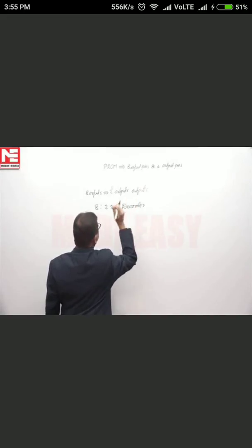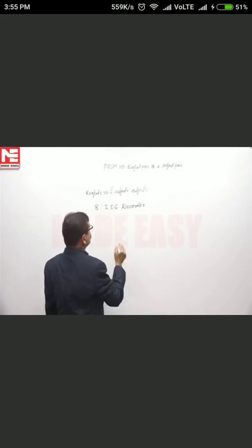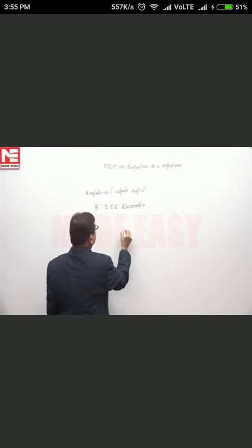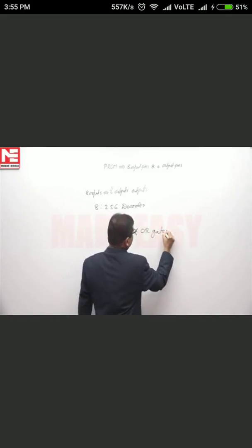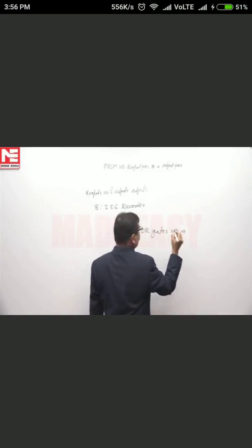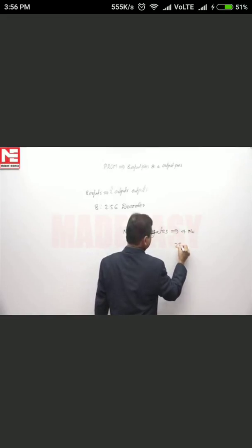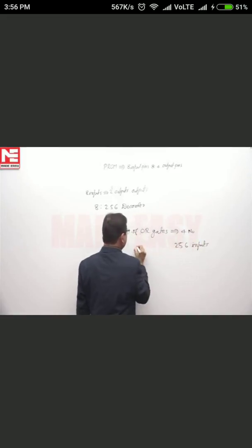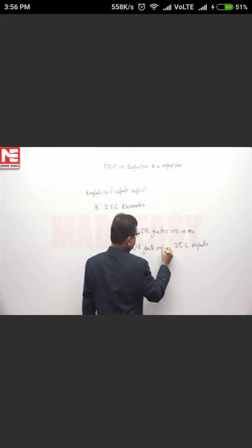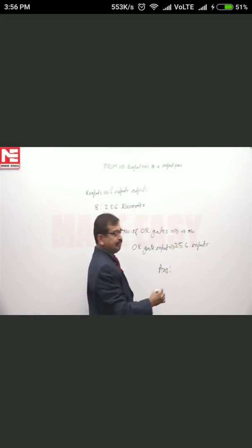So each output is basically a minterm on these 8 inputs, and we are having the PROM with 4 outputs, so that we are in need of number of OR gates 4, and each OR gate with 256 inputs. So the fan in for each OR gate will be 256. So based on this, the matching answer is option D.